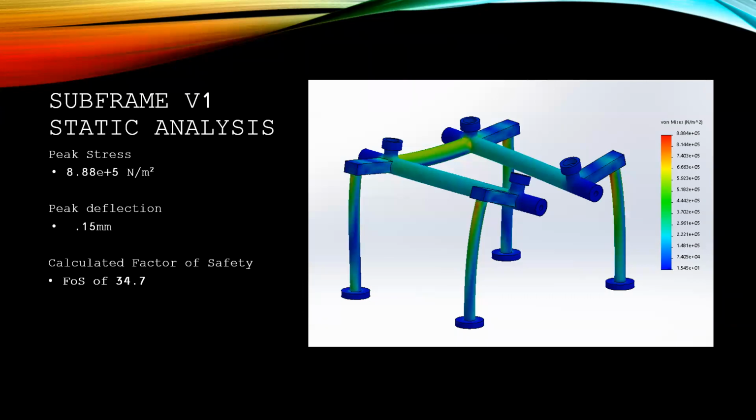With the appropriate material property of yield strength, we were able to estimate the approximate factor of safety, which is simply defined as the ratio of the material yield strength over the applied maximum stress undergone. A higher factor of safety indicates that the body could sustain higher loads than those applied, while a lower value indicates that the body could endure less applied load before failure.